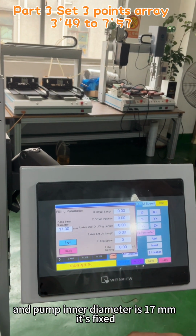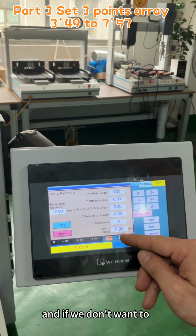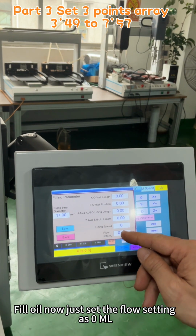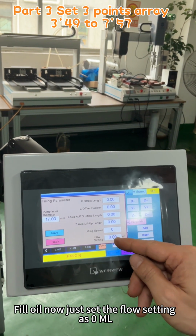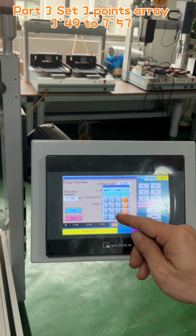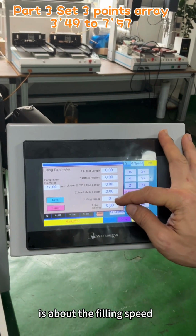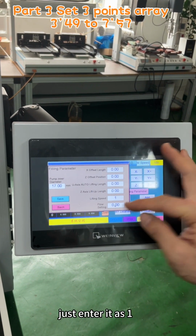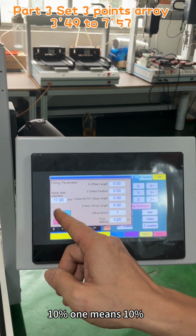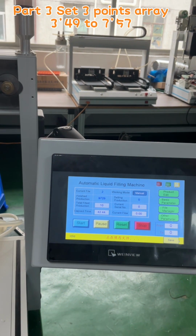And the pump inner diameter is 17 mm. It's fixed. And if we don't want to fill oil now, just set the flow setting as 0 ml or about 0. And the lifting speed is about the filling speed. Just enter it as 1. It means 10%. 1 means 10%. Just save it and back to the last page.